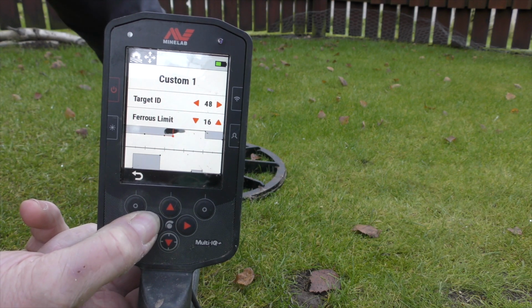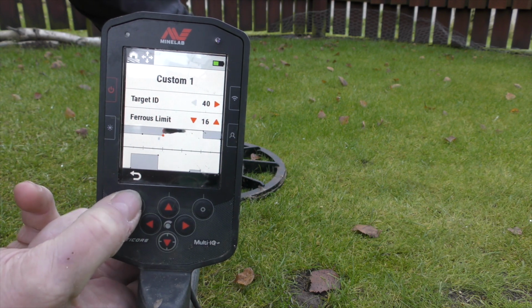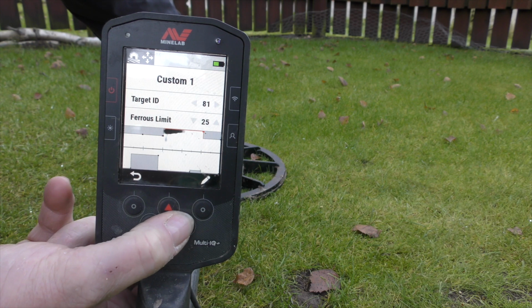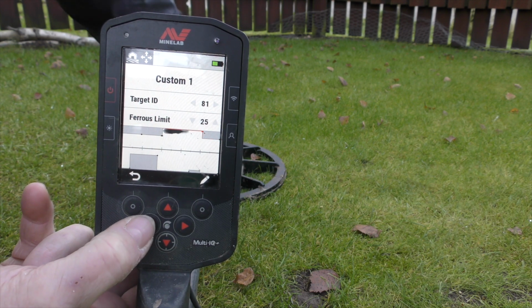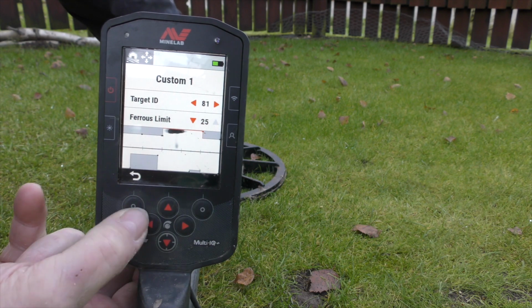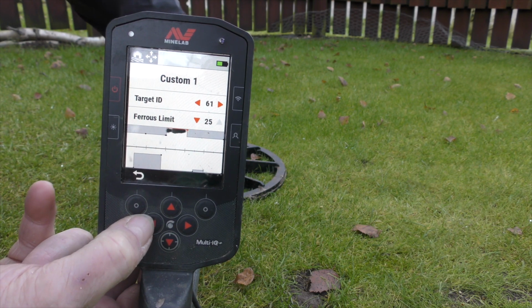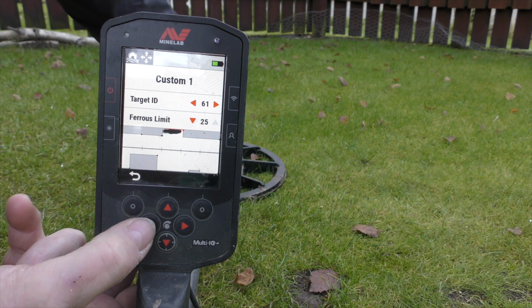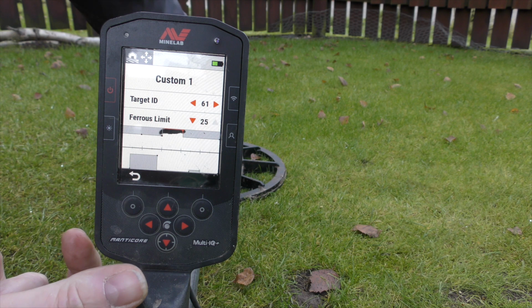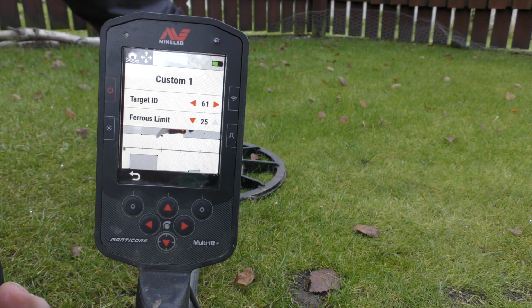Press the arrow keys to navigate to the region nearest to the coin trace and then press the right soft key. Wave the coil over the coin at a range of heights, adjusting the ferrous limits until all of the target trace is captured inside the gray area. To be thorough, you can also change the orientation of the test target a few times in between swings to capture all the trace variation for that target. You may need to adjust adjacent regions to capture any last parts of the trace.